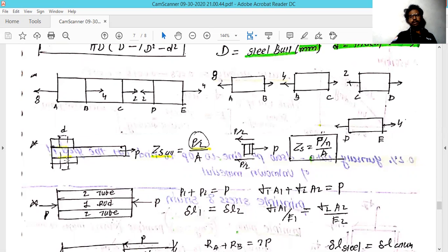Similarly, this is another cross section which is shown, which is simply the cross section of the bolt, which is cut with that rod. In the same fashion you can draw it for that rod as well. So here, this is the shear force which we are calculating. It is for the nut which is getting sheared, not for the rod. If the rod is getting sheared, that means the rod has a weaker value, and it tears up when you apply the force at the P point.